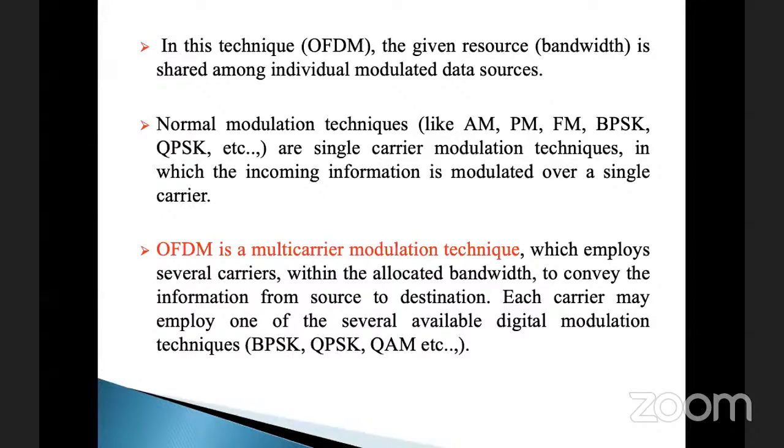This is happening because of the nature of your channel, which is a frequency fluctuating channel. To avoid that, we want to communicate in a normal flat fading channel. So what is a flat fading channel? A flat fading channel, irrespective of the frequencies you are sending, gives the same uniformly distributed signal across the channel. That means your channel is flat during your entire band of operation. But when you move to high frequency bands, the channel is not flat. It becomes a frequency selective channel.